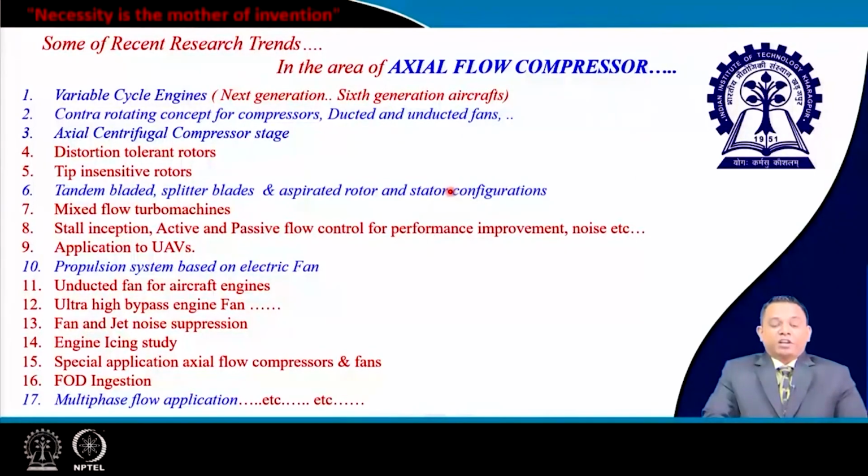Then tandem bladed, splitter blade, aspirated rotor and stator configurations, mixed flow turbomachinery, stall inception, active and passive flow control for performance improvement and noise, application to UAVs, propulsion systems based on, say, electric fans, we have discussed this part, unducted fans for aircraft, ultra high bypass ratio fans, fan noise suppression, engine icing study, special applications of axial flow compressors and fans, FOD ingestion, multi-flow application.